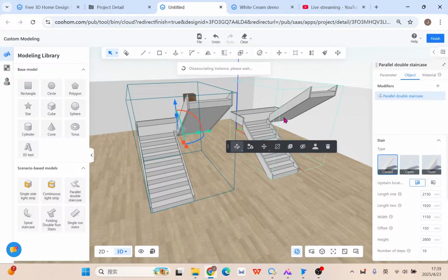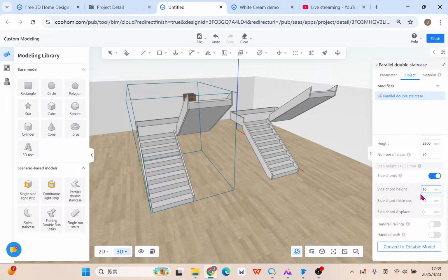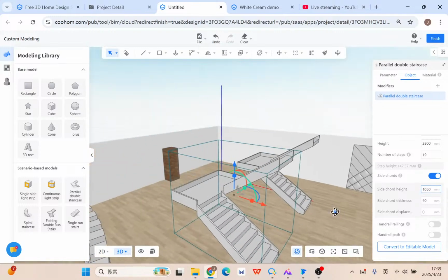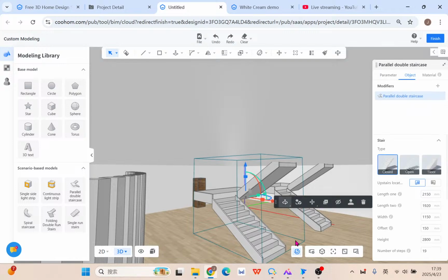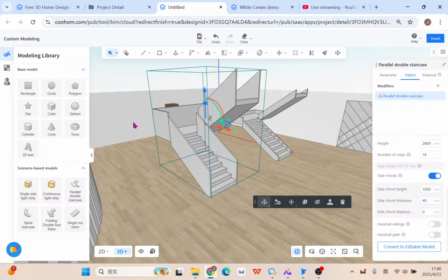You need to disconnect these two, otherwise whatever you change here changes again. So now turn to the cycle changing. The previous thing you have is the cycle height. This time, maximize them to the height of the railing, for example 1050, let's say. Cycle height, click, let me check. Yes, this one. Now the cycle height goes up, and then thickness, for example, 20.